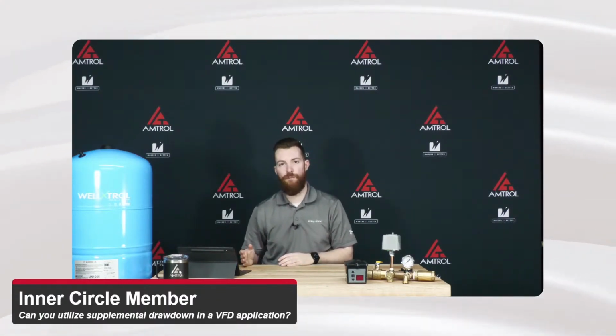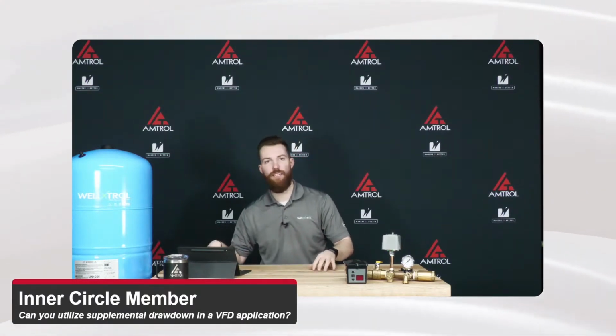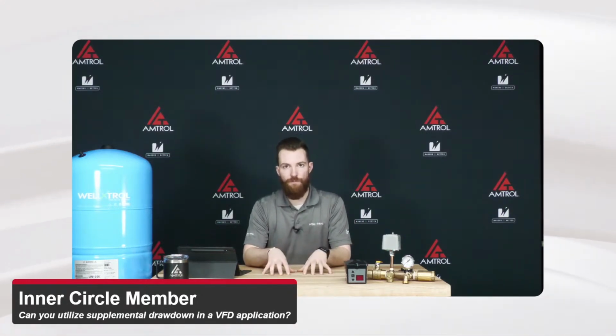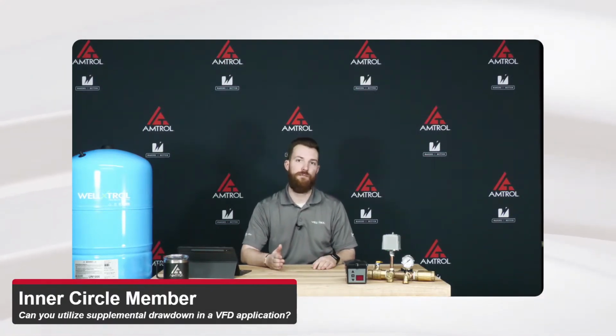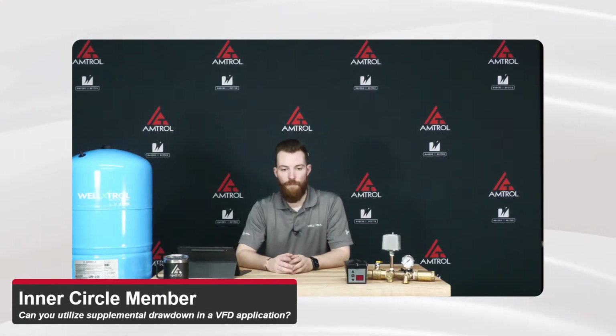So if we're sizing a booster system for a municipality, we know that our peak demands are 6:30 in the morning and 5 o'clock at night because people are showering and cooking dinner and whatnot. So we'll be able to estimate what that flow demand is, see where it fits on that pump's curve. If it's okay, we're still in the efficiency range, or if we're going to need some help, we'll be able to size the tank to make sure we bridge that gap, and their customers are going to get steady flow and good pressure the whole time. That's one way to do it.